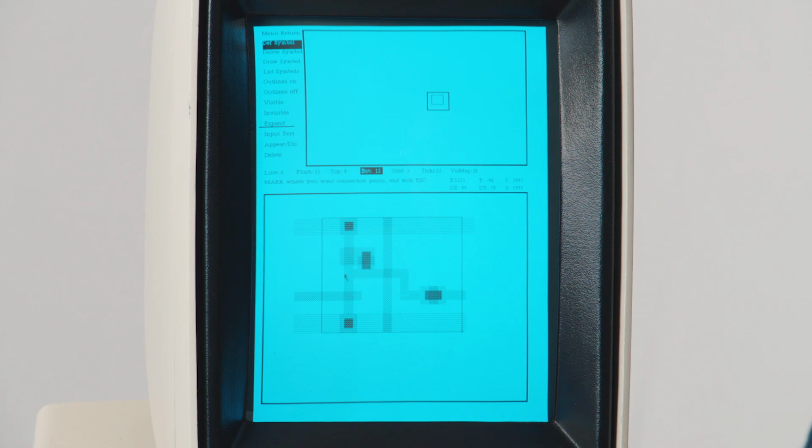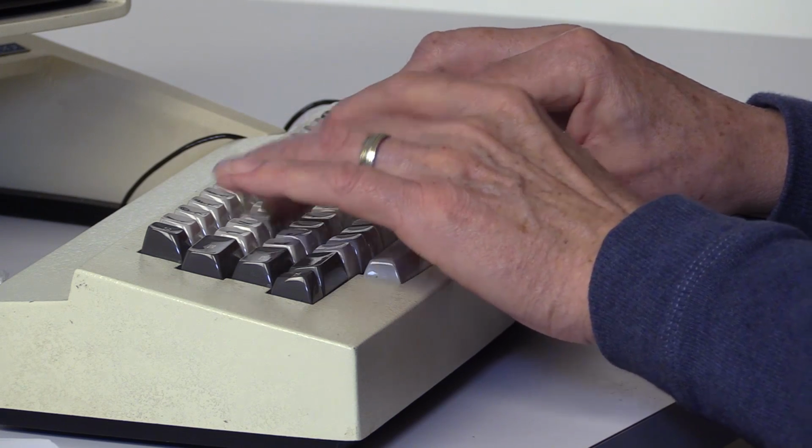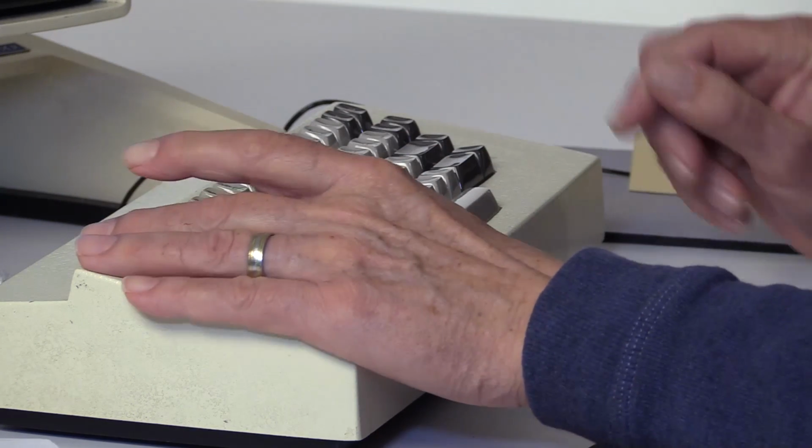And then you can define what are called connection points, because later on it's going to make these items invisible, and all you're going to want to know is where can I connect to the symbol. So I'll say, well, I want to connect on the input, I want to connect on the control line here, I want to connect on the output, and I want to connect on the bottom of the control line there. So those are all my connection points, and I type escape, and I'm going to call this cell 1.